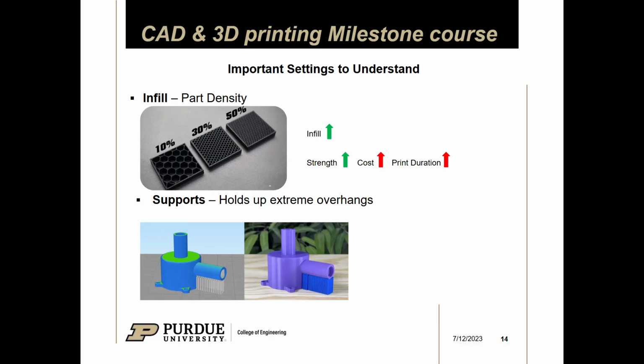As a designer, you typically can design things to not require supports, right? So one of my challenges for you when you're making your finals is to try to limit the amount of supports you need. Most of the finals I get don't need them at all. If you design things properly, you may not need them. Obviously, if your geometry has to be a certain way and you need supports, you're just going to have to use them. But because you have the power to design things, you can try to design them out.